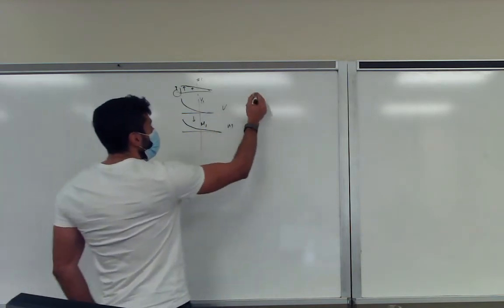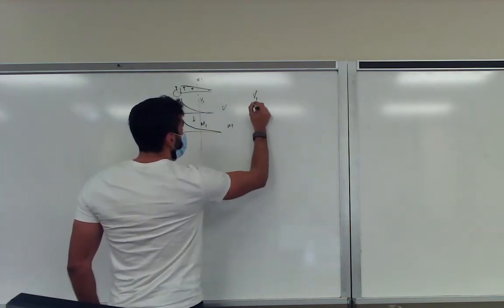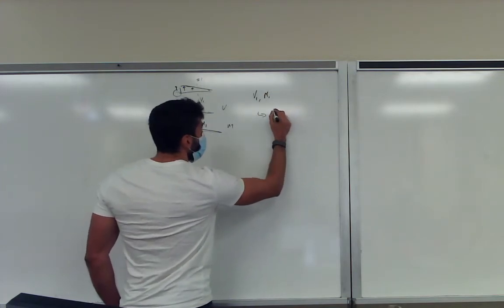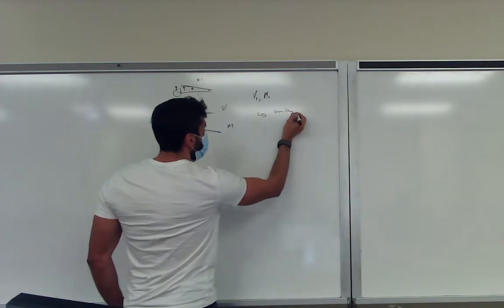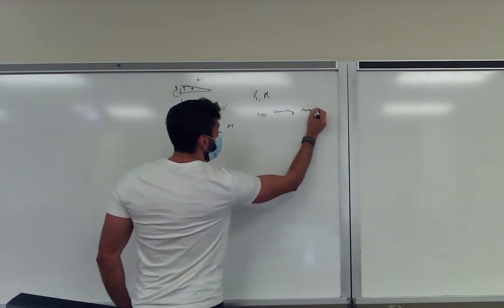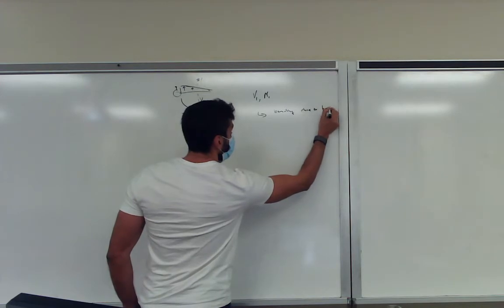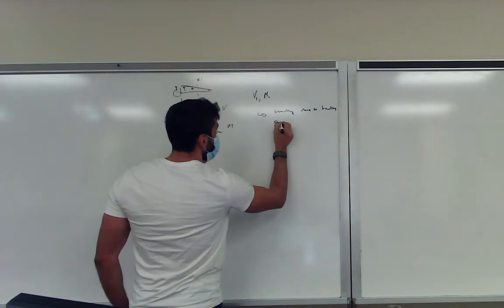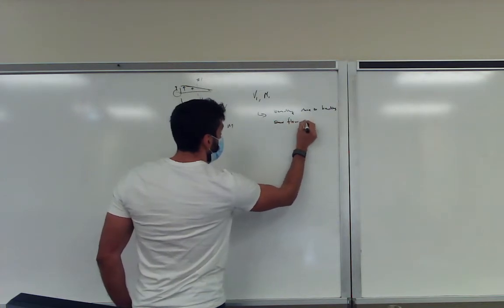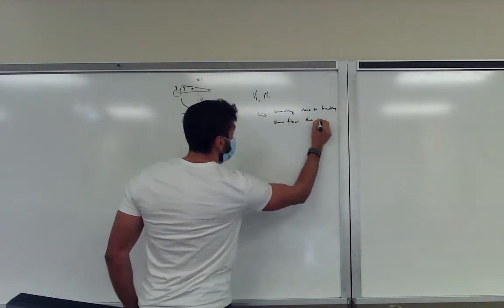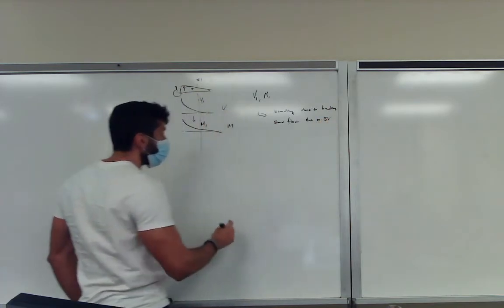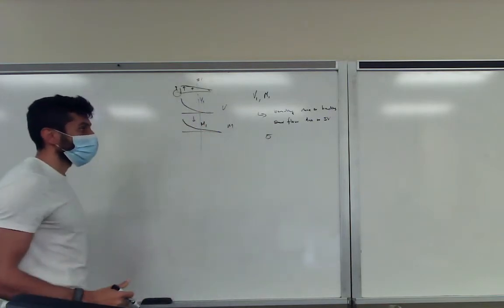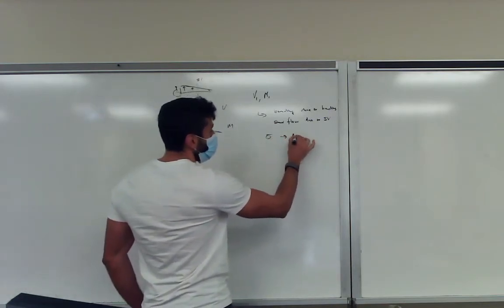Then we can use these forces, V1 and moment 1, and plug them into our bending moment equations due to bending. We can put it into our shear flow due to a force, and then we can get our stresses and superpose them, and then we can determine if it fails or not.